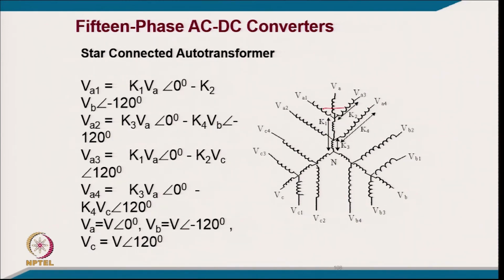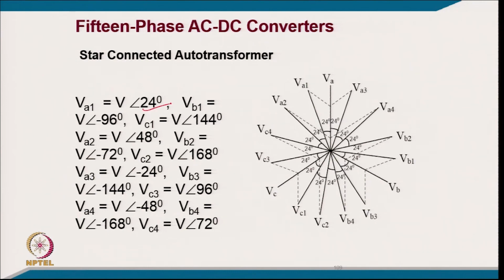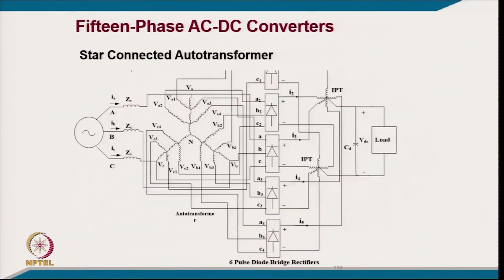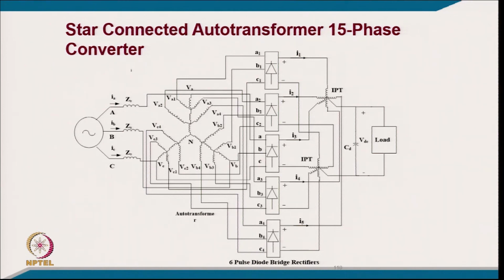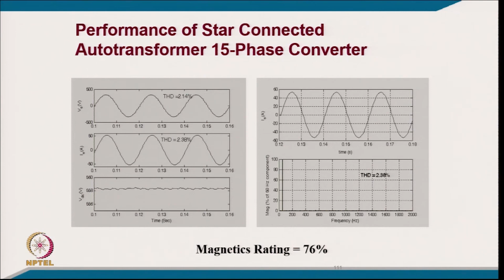As you can see here, what is the original and what is the different degree, you are getting 24° from this. 15 phase means 30 pulse, where you are using 5 converters connected in parallel with the 15 phase supply. Each bridge is getting virtually from 3 phase, so 15 phase means 5 bridges. You again have to use an interphase transformer so that all are conducting, but if you are not using it, only one bridge will conduct. So that also will distribute the current equally among all.